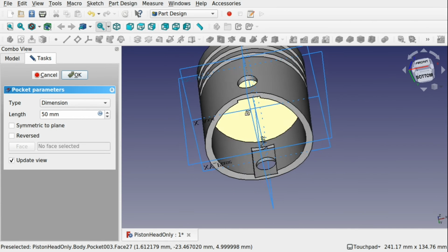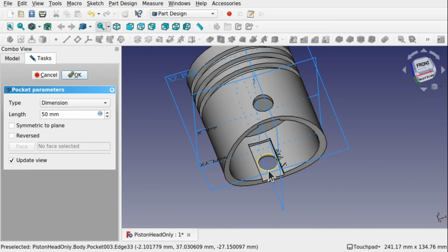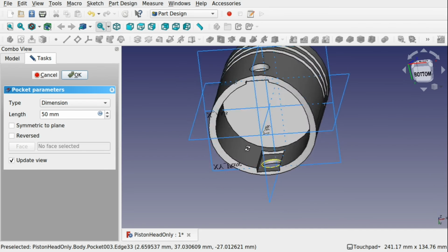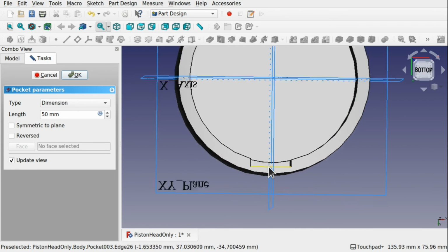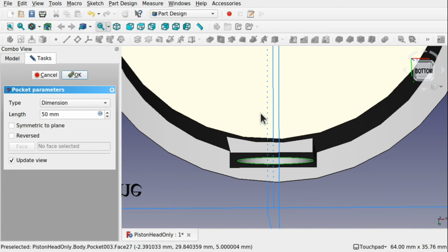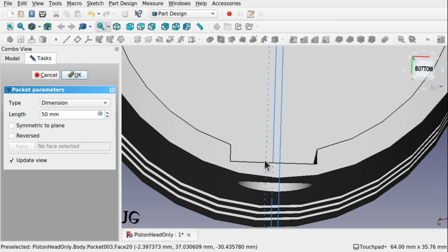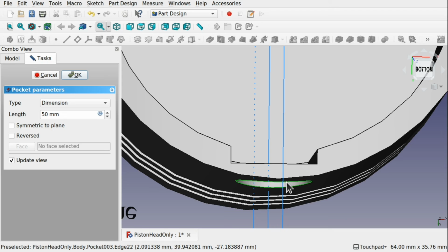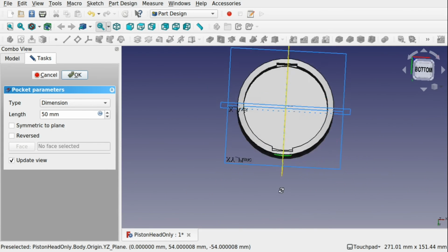And that's taken a slice across there. So you can see that if I was more accurate with that pocket, that will now be coplanar. So if you look at this from that way, you can see that's nice and straight. That means we can create a circle and circle constraint on that in the assembly workbenches. Whereas this side, you can't get a circle and circle constraint because it's not a planar circle. So that's one thing to look out for.